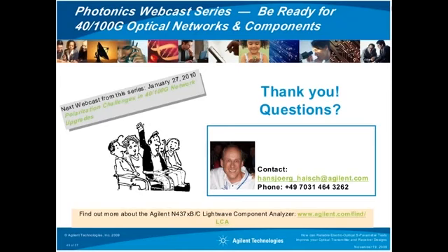I would not consider it an S12. The overall transmission performance is depending on external reflections. I think you probably refer to reflections that exist between the optical output interface of the device under test and, for instance, the optical input into another component. So you have forward and backward reflections.